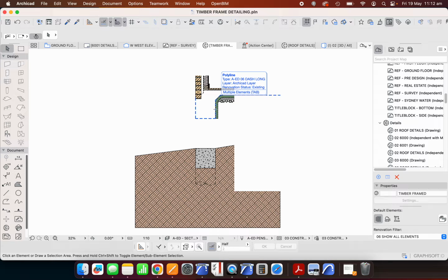Now, this is a little bit tricky if I want to go to this level of detail. The mortar joint is continuous, and it can still have a raked outer edge. The line should be thinner because it's in elevation, not in section. And this brick isn't going to be seen with these diagonal lines. In this case, it's going to look like a brick should look in elevation.